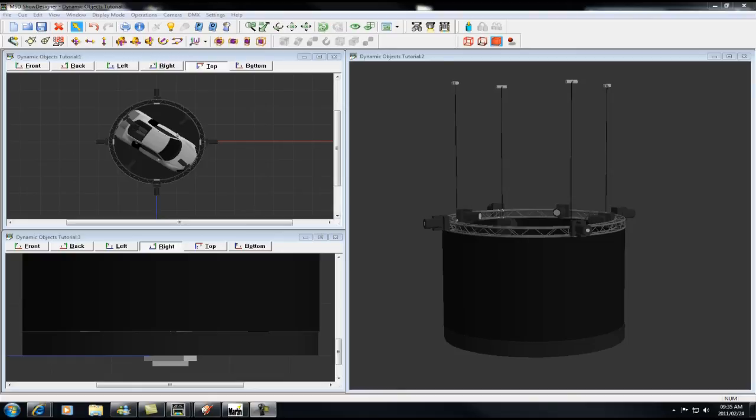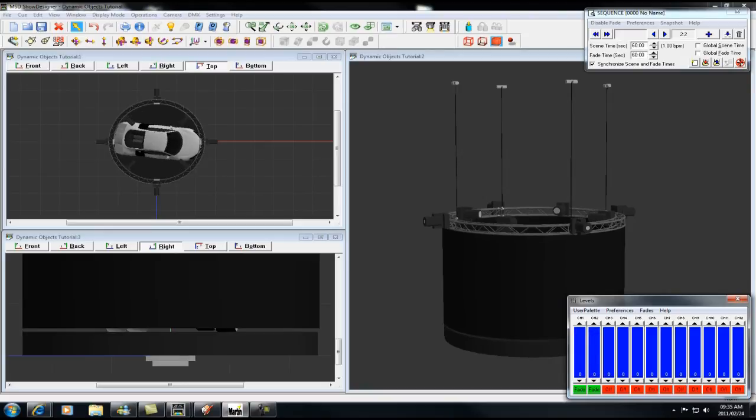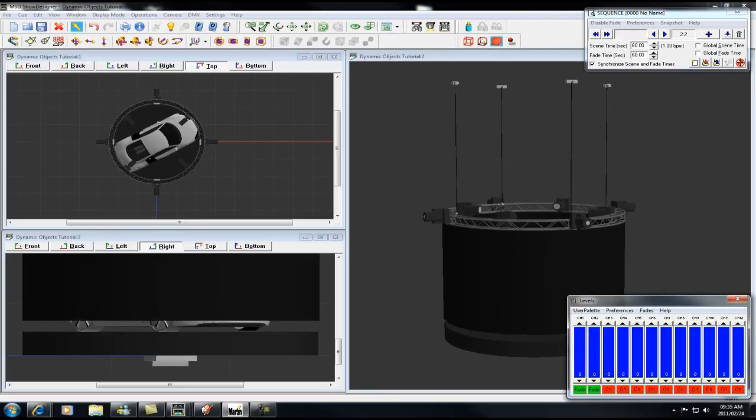Once again, I have set the address in Light Jockey DMX1 to the rotator and DMX2 to the hoist. You can now see that in my sequence queue, the first ones are set to maximum value. I can put in a time there. I'll add in a step, pull those down, also do it over 60 seconds, and now you can see how the animation is working.